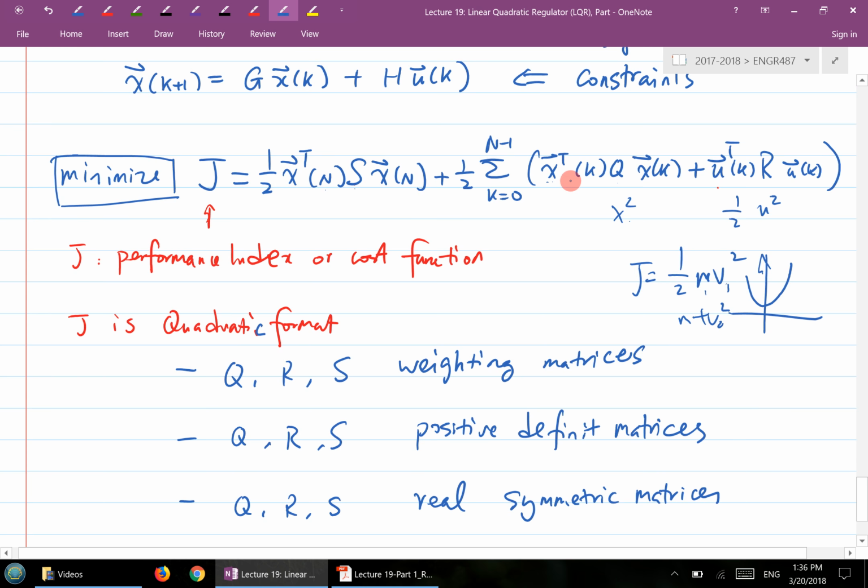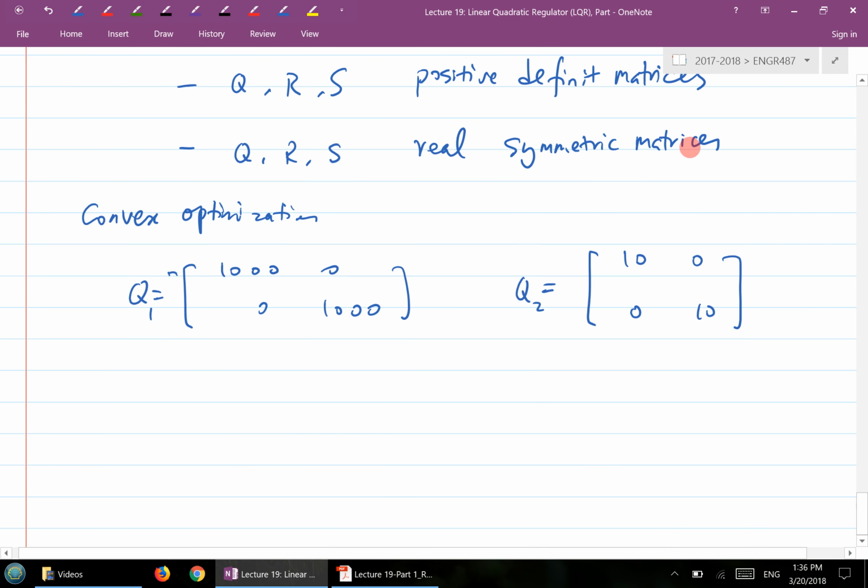So this gives you a sense, in the future when you do simulation or control, of how to pick a Q or R. If you want very small errors for X, or basically want to bring it back to 0 as close as possible, then you need a larger Q value. Does that make sense? So how about the R?